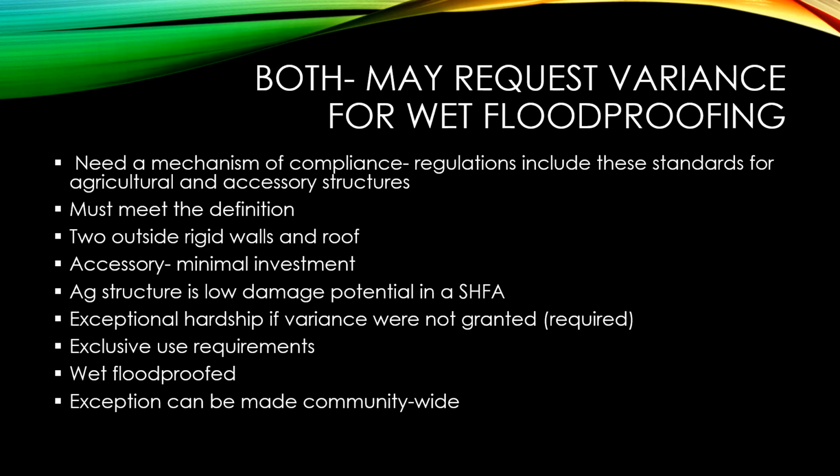As Steve reminded me, I didn't say for agricultural structures, they need to be single wall construction to meet that definition as well. And so, again, criteria for this include hydrologic and hydraulic data, which could include our flooding conditions, the duration, frequency, depth, warning time, safety, and access. It details how to request an exception for the community, and the FEMA regional office will inform the community if it's granted, and the same thing goes for accessory structures.